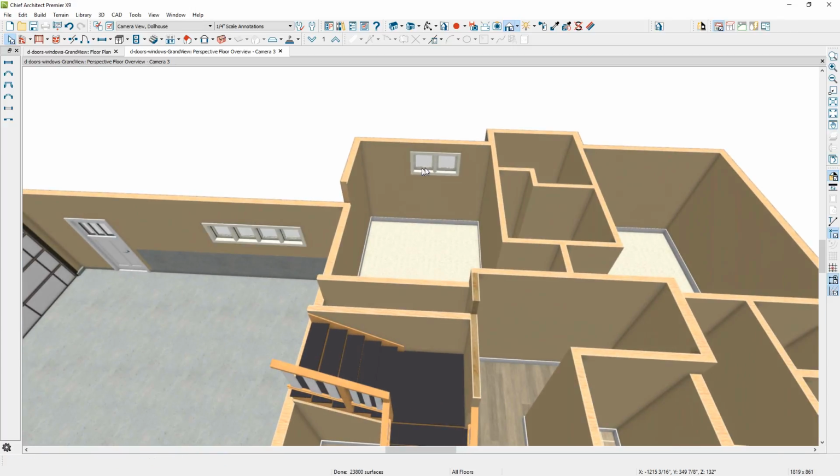I'm going to take these 2 windows here, and let's go ahead and center those in the room using the center tool. And again, before I create a block of those, I'm going to take one of those windows and create a copy of it. Control C on the keyboard, Control V over here in the Jack and Jill bathroom. Now I can block these 2 windows using the block command down here, and then copy and reflect about the Jack and Jill, and that will put it right in the center of the other bedroom.